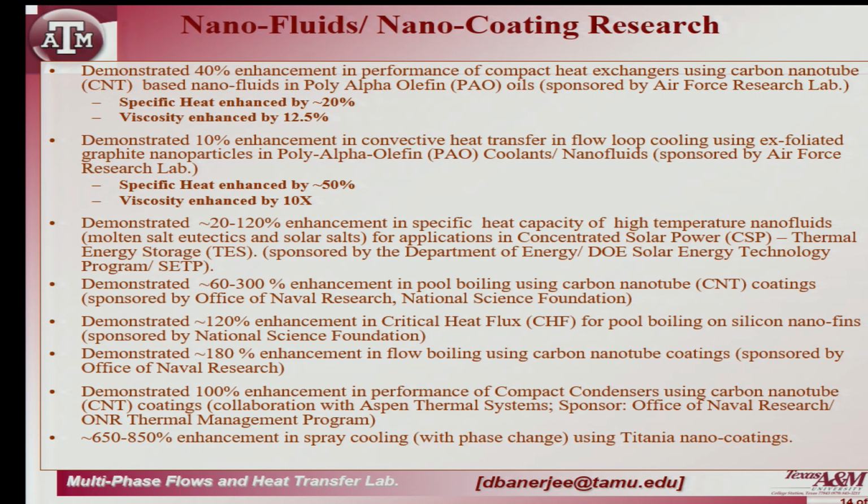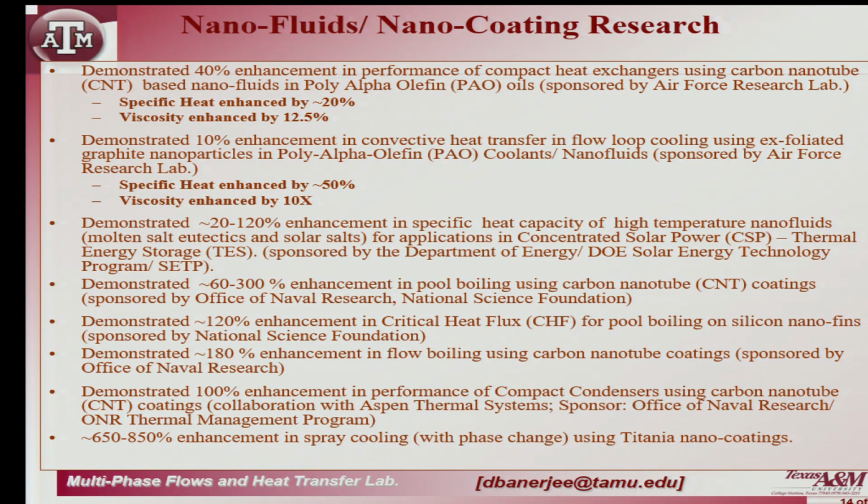Nanotubes have a very high thermal conductivity, so maybe it was enhancing the efficiency of the heater in conducting the heat into the fluid. So to test this hypothesis, instead of using carbon nanotubes, we decided to use silicon nano fins. Okay, and silicon has a lower thermal conductivity than carbon, and we were expecting the amount of enhancement we would see in the CHF to be lower in silicon than in carbon. And then to our horror, we found the CHF went up by 120%, double that of carbon nanotubes. It didn't make sense because silicon has a lower thermal conductivity.